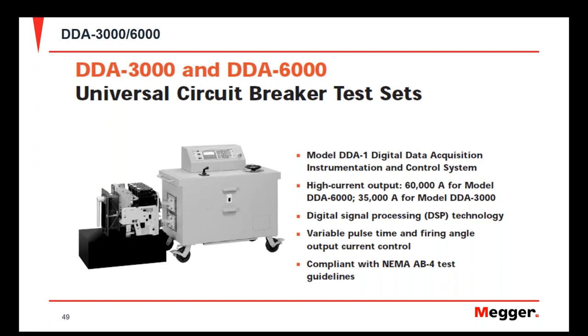Both units are operated by the DDA1, which is a digital interface used for breaker testing, but it also offers the ability to have variable pulse time and firing angle to negate the influence of some of those challenges that we talked about whenever you do primary injection testing. Also, this test set is compliant with NEMA AB4 for breaker testing guidelines.